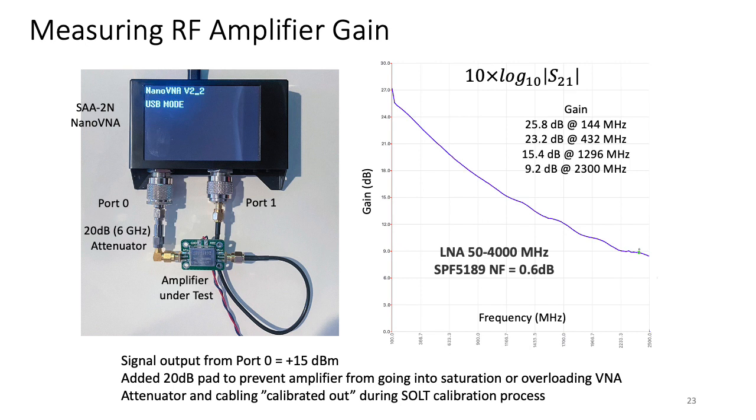So in order to make this measurement, what we're going to have to do is set the measurement plane to be here for the input plane and the output plane to be on the other end of the amplifier. In doing so, by putting the short, open, load at the output of the 20 dB pad, we remove the effects of the 20 dB pad, and similarly we remove the effects of the coaxial cable at the output of the amplifier when we make these measurements.